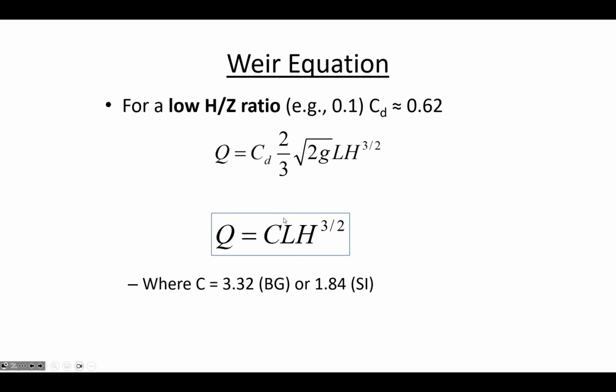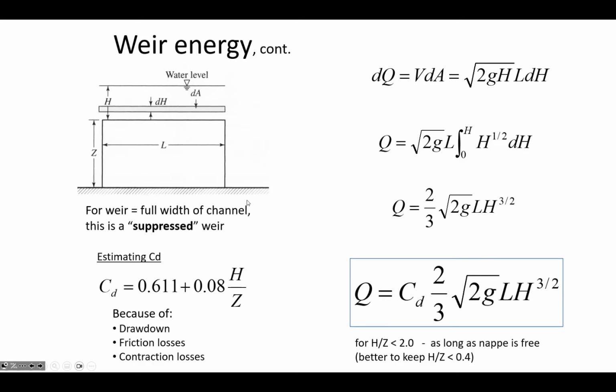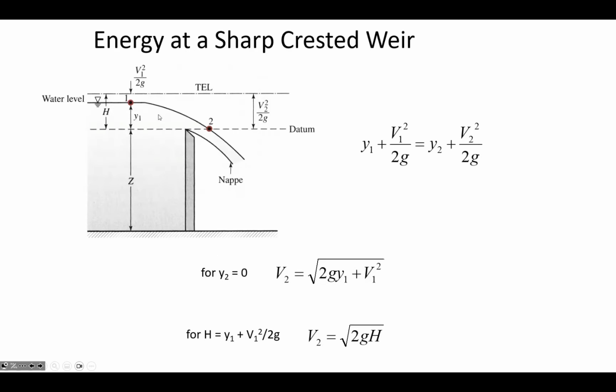And then you could put in the length either in feet or in meters, and then the H term would be also a distance in meters. And H, remember, is how far is it from the weir up to the water surface. And this water surface that you're measuring from the side view is before the drawdown occurs. So H, if you look, is going to include some amount of velocity head, but typically for slow-moving flows, most of H is just the depth itself.